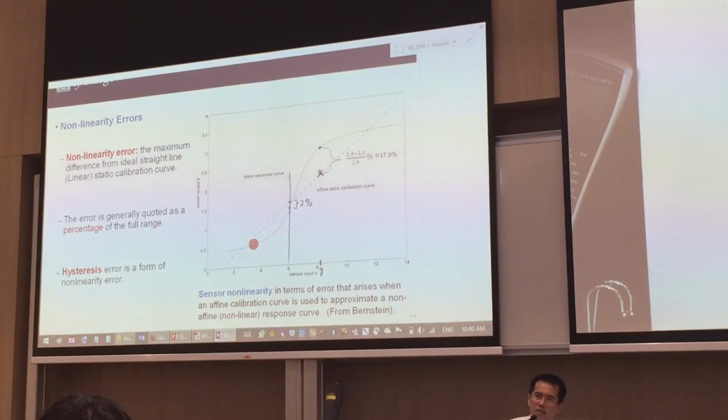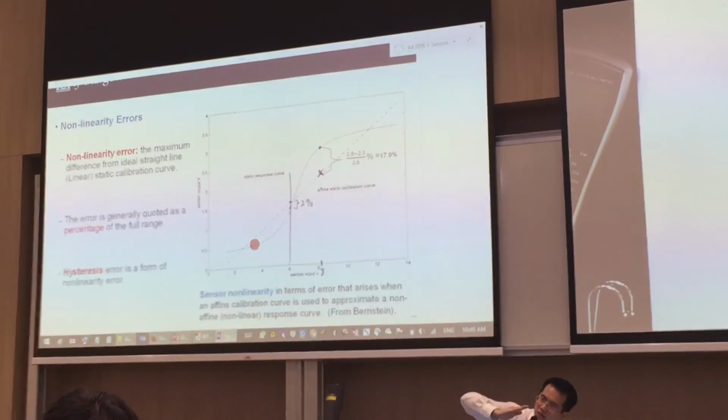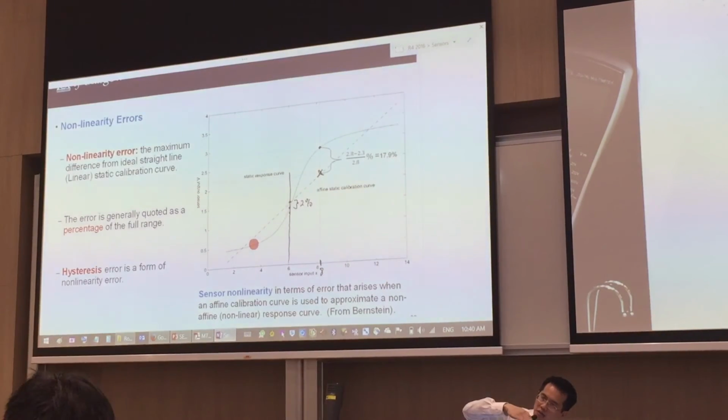So certain cars, they would design it maybe with a linear response. Certain cars design it with a slightly nonlinear response, because it's harder to use our foot to control. Right? Because your foot, when it's down at the car beside the accelerator, is angled. The amount of swing that you need when the foot is angled is different from when it's straight and you swing.